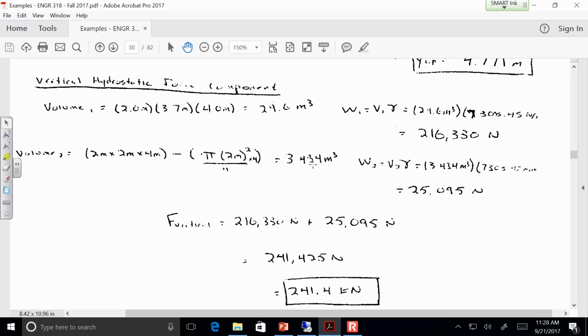You've got the formula for the location of the quarter circle, and we know the location of the rectangles in the middle, so you'd use the weighted average technique to find out where that component is. And then you would do another weighted average to say I've got this much force in the middle and this much force offset sideways. You'd multiply the magnitude by the location and divide by the total magnitude.